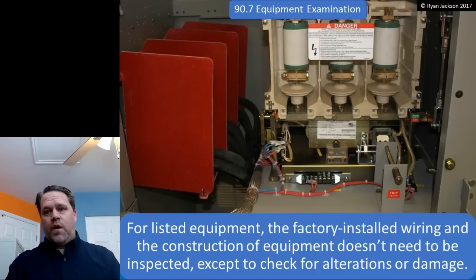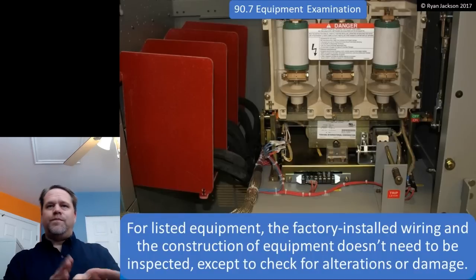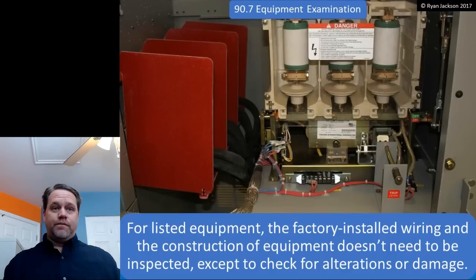approval of the equipment. Yes, you altered that luminaire. How did you alter it? Well, the screws that came with it, mounting screws, were 2 inches long. I cut them down to 1 inch and then I put them in. Did you alter the listed product? Yes. Did you alter it in a way that's going to matter? No. So I'm still going to approve it.